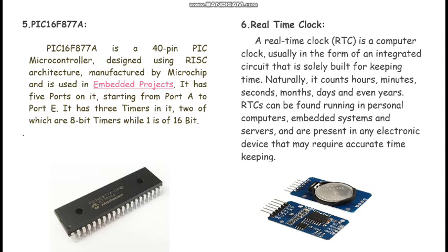Fifth one is a very important component, that is the PIC16F877A. PIC16F877A is a 40-pin PIC microcontroller designed using the RISC architecture, which is manufactured by Microchip, and it is used in many embedded projects. It has 5 ports, starting from port A to port E. It has three timers, two of which are 8-bit and one is a 16-bit timer.